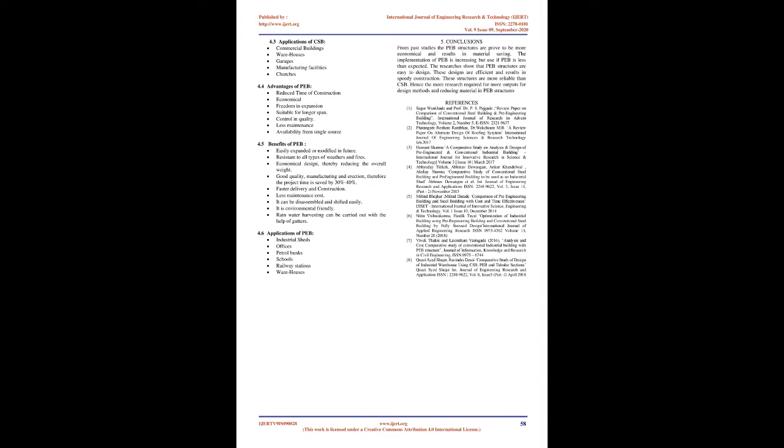8. Swati Wakor and N.C.W. have shown that using pre-engineered structure in construction has various advantages because the designing of members is done according to the bending moment diagram. As a result, the steel is reduced. They have analyzed and studied according to IS 800-2007 and IS 800-1984, and the comparison of pre-engineered structure with conventional steel structure is done. They have also compared the weight of both the structures. From their studies they concluded that conventional steel structure is 30% heavier than pre-engineered structure, and as a result the size of foundation is reduced for the pre-engineered structure.